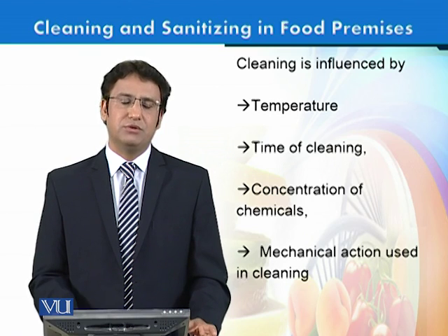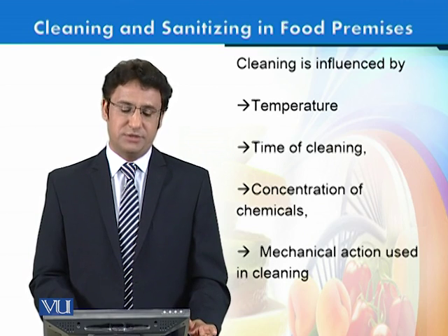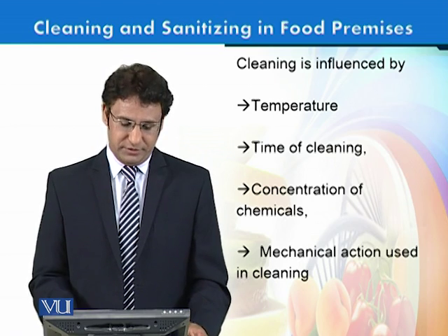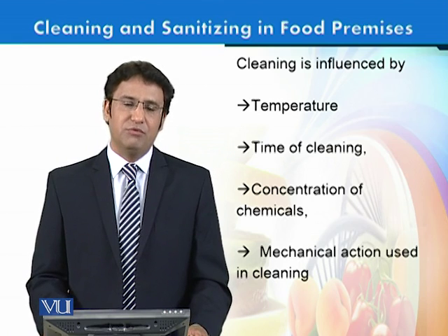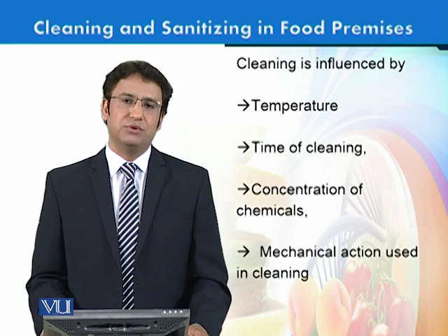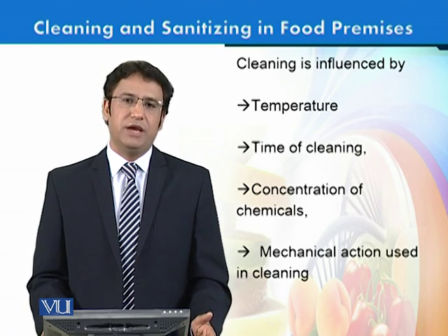So we have to follow those given instructions to use proper concentration for a sufficient amount of time and the temperature as well. Only then would they be more effective. Then we have to look at the mechanical action used for cleaning. If we use more mechanical action, then maybe we can reduce time and the efficiency of the cleaning might be improved.